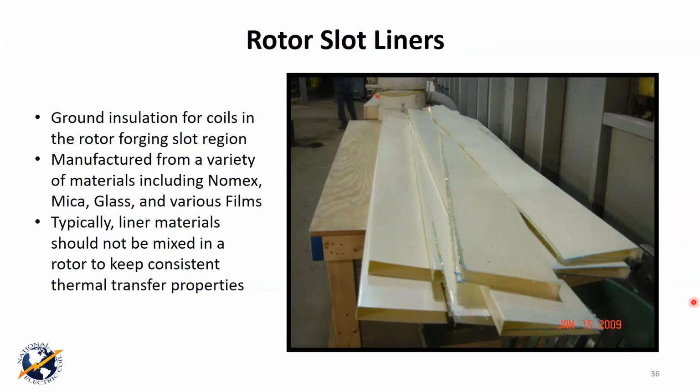Ken asked if all rotors have a center bore hole for using a bore scope, and the answer is newer units most likely not. The older units do, because the hole was used to do 2 things. One, it bored away the impurities or inclusions that could lead to stress cracks during later operation of the unit. And over time, they could go down that area that was relieved and machined out, and they could hone the sides with a hone, just like you'd hone a cylinder on an internal combustion engine, if you can understand that analogy.